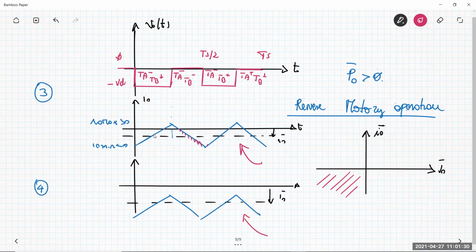And it is the same behavior as in the situation in which the total current is positive. So there is no more distinction between continuous conduction mode and discontinuous conduction mode for this bidirectional converter. The current can always flow, because we employed bidirectional semiconductor switches that are able to support current flow in both directions.